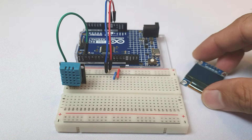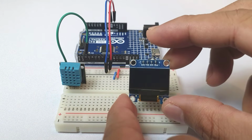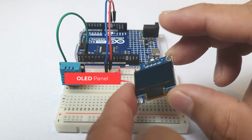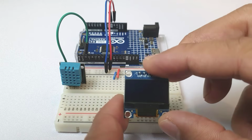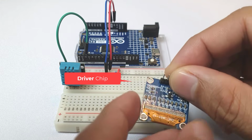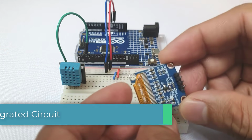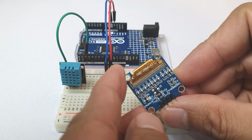For the OLED display, the one included in the SunFounder kit is an SSD1306 I2C OLED display. This OLED display is made up of two key components: an OLED panel. This thin panel comprises tiny pixels, each containing organic materials that emit light when an electric current passes through, and a driver chip mounted on the back that controls the pixels using an I2C or Inter-Integrated Circuit Communication Protocol. This chip interprets signals from Arduino and translates them into commands for the OLED panel to display.